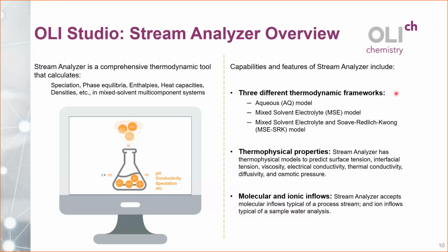So we have 3 different thermodynamic frameworks to calculate these properties: the AQ framework, the mixed solvent electrolyte framework, and the mixed solvent electrolyte and Soave-Redlich-Kwong equation of state. That basically is the MSE-SRK model. We will probably go through all of this just to explain when to use which in our applications. We will also be learning how to enter molecular and ionic inflows to represent our corrosive environments, and that is all possible using the Stream Analyzer.